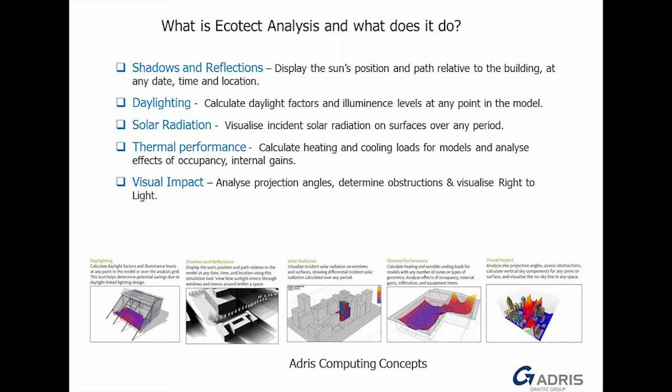Daylighting: calculate daylight factors and luminance values at any point in the model. So how much of the outside daylight is actually penetrating into our building. Again, very simple to use. Solar radiation: visualize incident solar radiation on surfaces over any period. So how much solar radiation is our building receiving? Which faces are receiving the most?